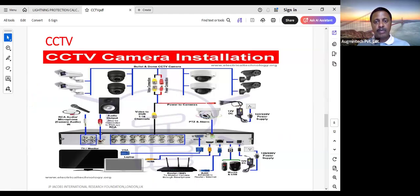But power wiring is required for both this DVR as well as your cameras too. This is an analog camera. The same thing, if it is of an NVR type, then it's going to be a digital camera. So the camera itself is going to process the image and then send the information towards your recorder with the help of Cat5, Cat6 cable.